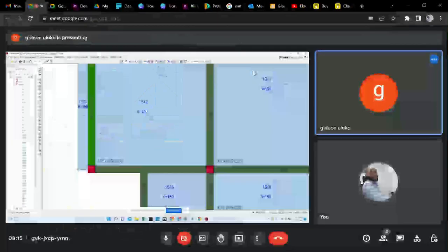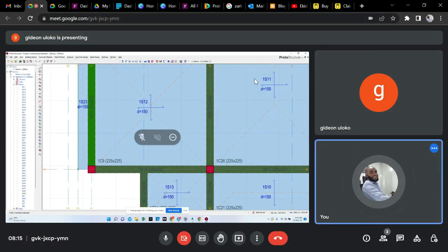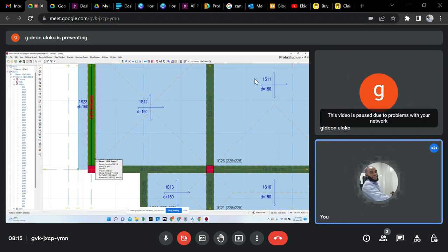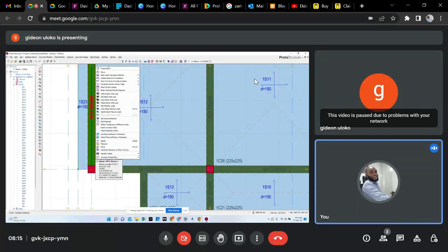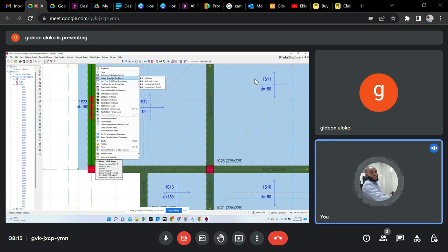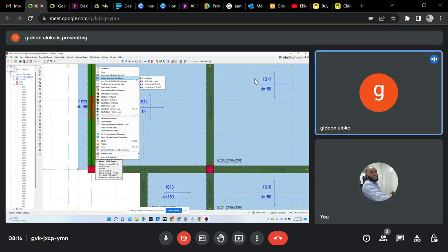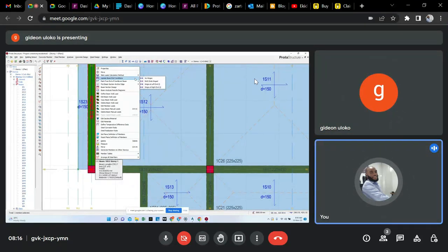Okay, so click on beam 12 right now. Right click on it and click on update beam end condition. Don't click that, just hover there, and you see now you have these four options, right? The first option is no hinge. The second option, hinge both ends, is for a simply supported beam, because both of the ends are discontinuous and not continuous.